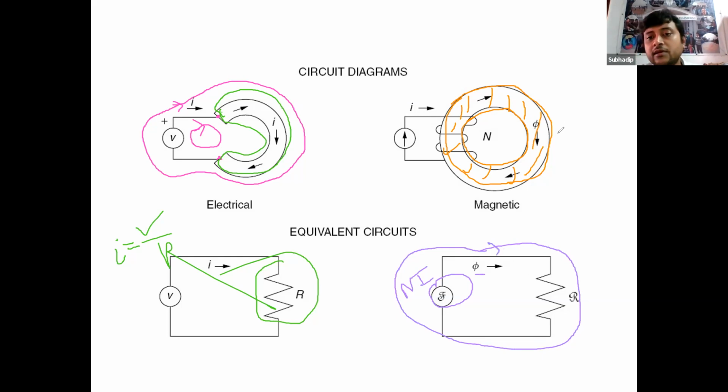As you know, this is a ferromagnetic material, a magnetic material which you can make an electromagnet, and the equivalent reluctance will be considered as Roman R. This is a particular reluctance value. Okay, this is the equivalent circuit.